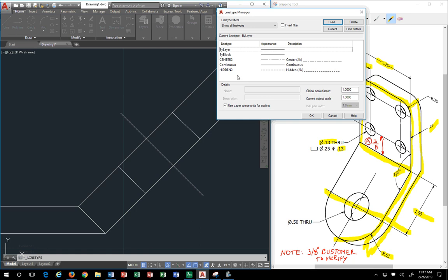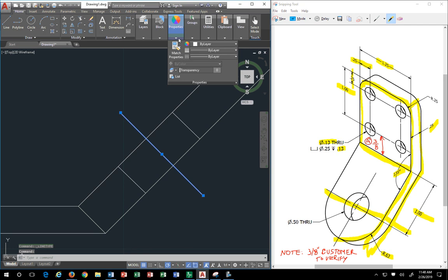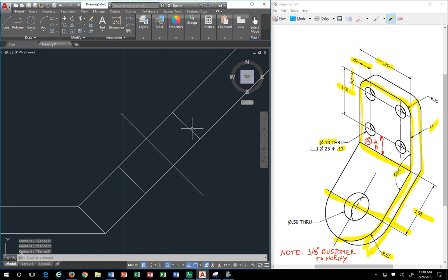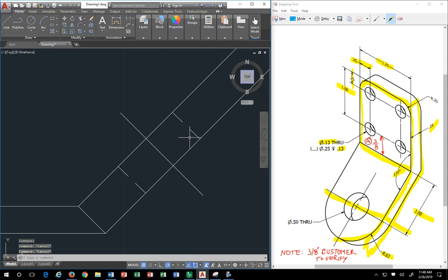Okay. What kind of line is it? Do we know yet? We don't. Because what did I do? Redraw it, right? So we're going to click on the line and make sure that it's center line. See that? Center line. At the same time, let's change the other 2 to be hidden lines. They're hidden, but you see how they turn into 2 little dashes. Not much change.